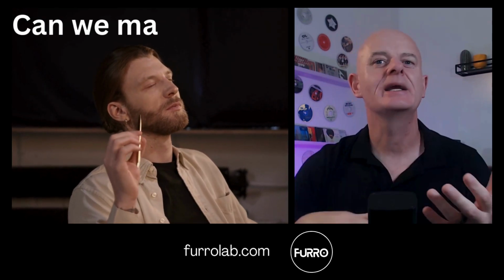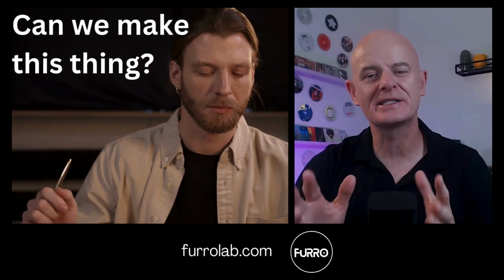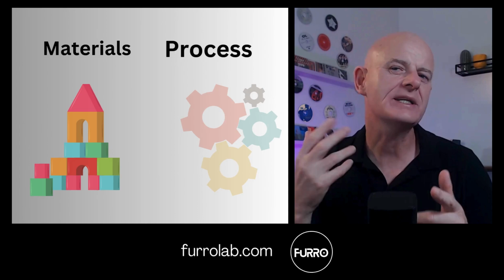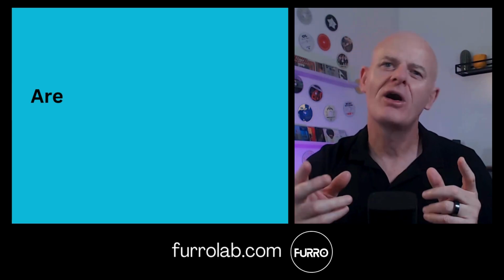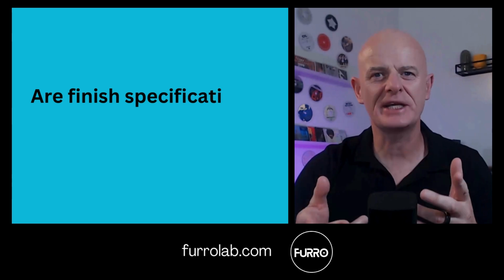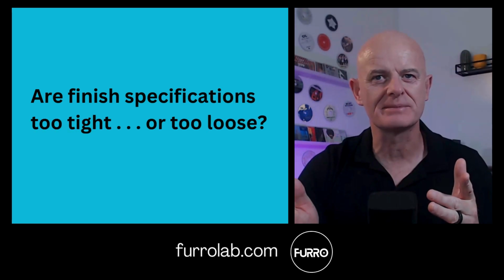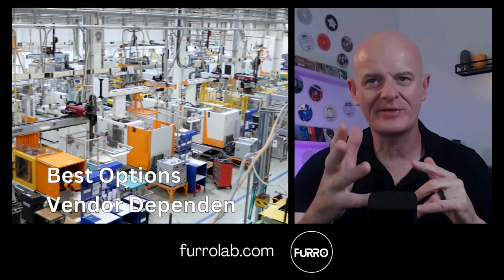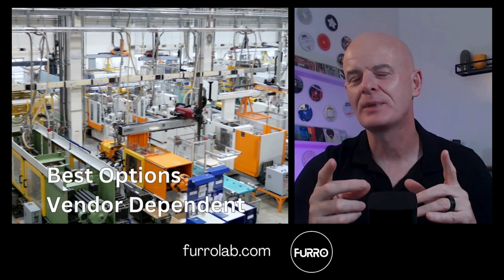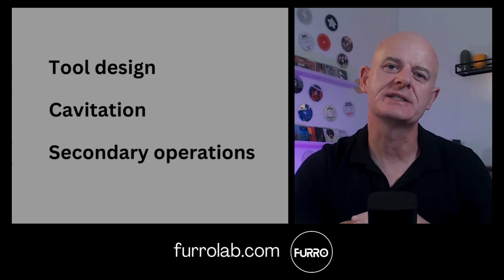Part design. Can we make this thing? And can it be made to the highest standard? Are we selecting the right materials and the right processes? Are the finished specifications too tight or maybe a little too loose? What's the best machine selection based on your vendor's plant and ability? This will inform tooling, things like cavitation, and even secondary processes.